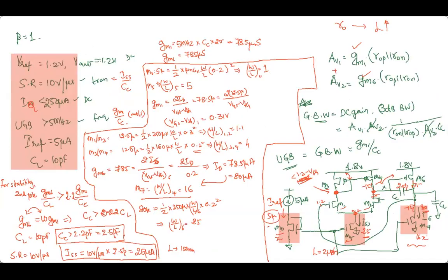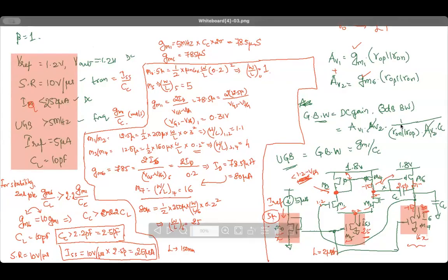We started designing with all the equations that we know, right from the currents that were given. We have some specifications given on the left. Slew rate is given, and the quiescent current of 250 microamps is given. A lot of specifications are given, and then we derived the sizing for all the transistors that are present here.